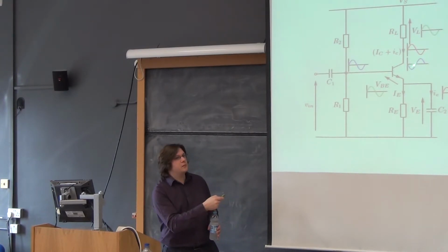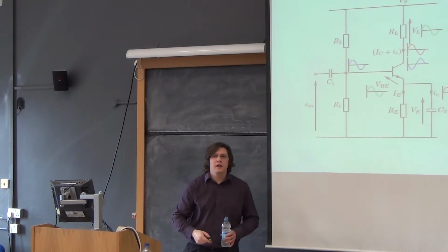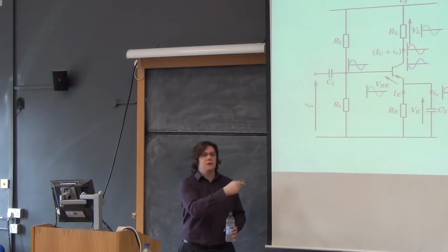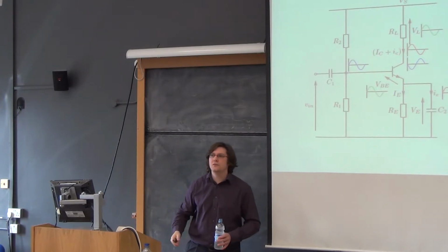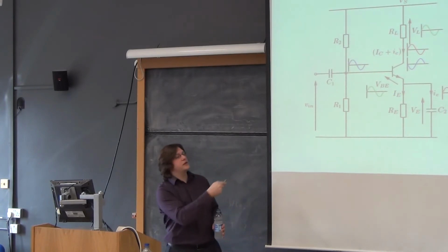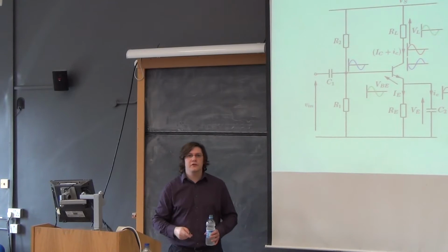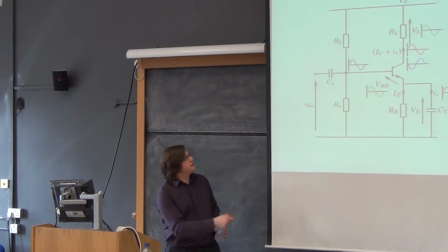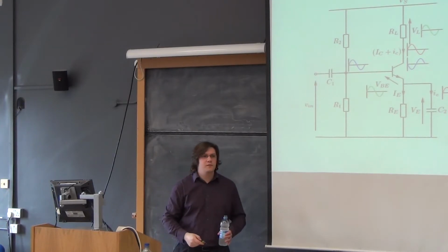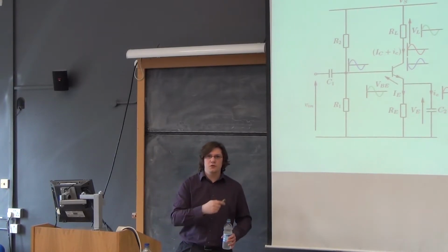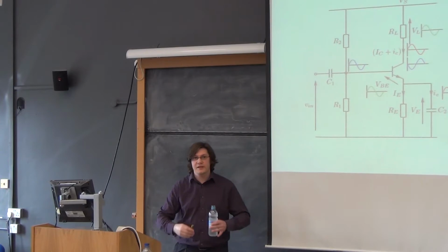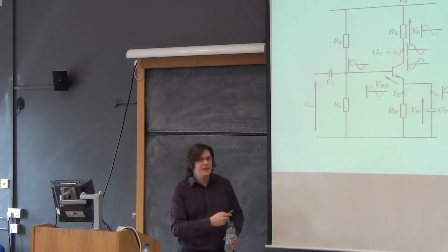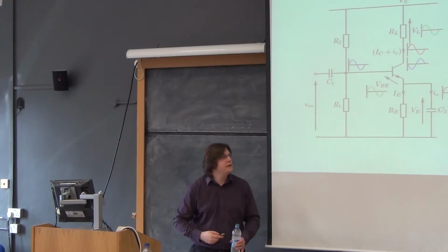And then the transistor would get a bit hotter because the current was flowing, and that would mean that the VBE that was needed to cause that current to flow would be slightly smaller than it was before, which would mean the current would get bigger, which would mean that the transistor would get hotter, which would mean that more current would flow, which would mean that the VBE needed to keep that current flowing would be smaller still, which means that more current would flow, which means the transistor would get hotter, and if I keep going, my head might explode. Much like the transistor. This will be thermal runaway.